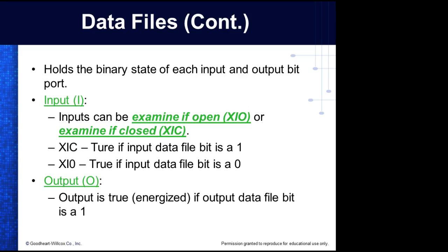If you're using the examine if closed instruction, and this only deals with inputs, guys, switches. This doesn't deal with contacts used inside the program. This deals with nothing but what you're inputting off an input port.